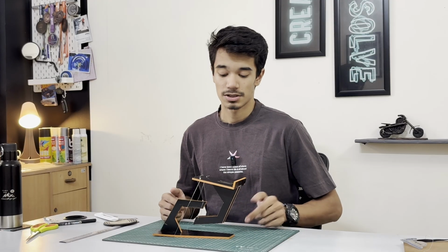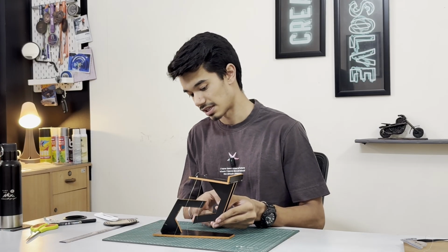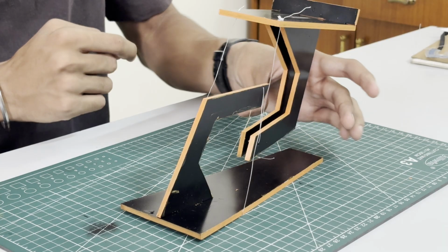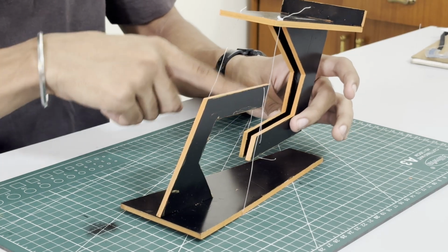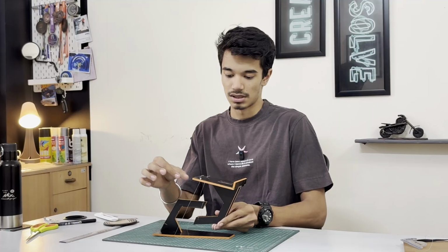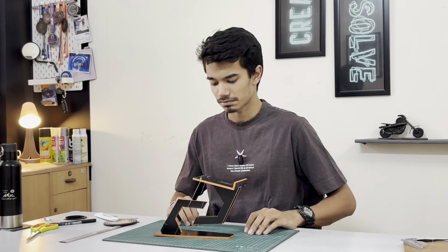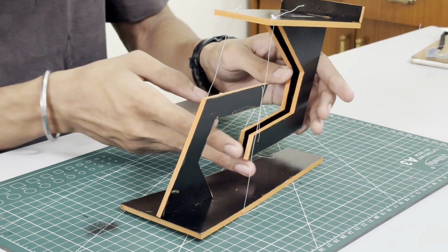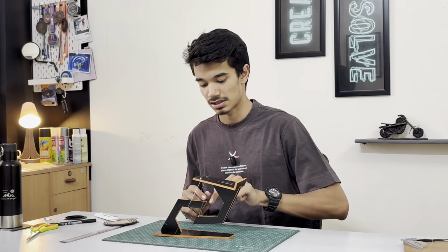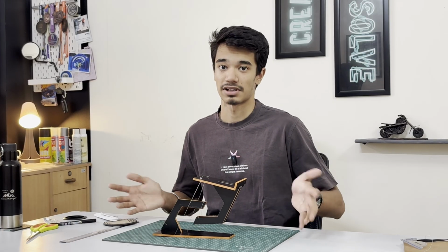And I think the solution to this problem may be in gluing all of this together and fixing these two flaps at a constant distance, since they have this tendency to come closer together as more weight is put upon this string. It pulls these closer together, and then the whole thing just collapses downwards. So I'll put a piece of sunboard in between them and see if that fixes the problem, and also glue all of these joints and glue the string in place, as I think it's at the perfect length right now.